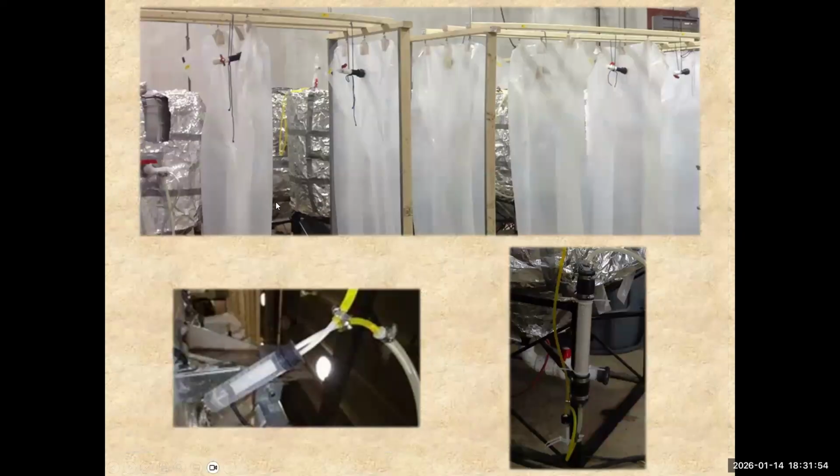And since our digesters couldn't take much pressure, we designed a separate biogas collection system using these 1,000-liter plastic bags that we installed custom-made gas collection ports on. As you recall, I previously mentioned that biogas contained a small amount of water vapor. So in order to prevent excess water vapor from entering into these biogas bags, we designed these moisture traps as well as these desiccant traps to capture some of that water prior to the gas going into our biogas collection system.